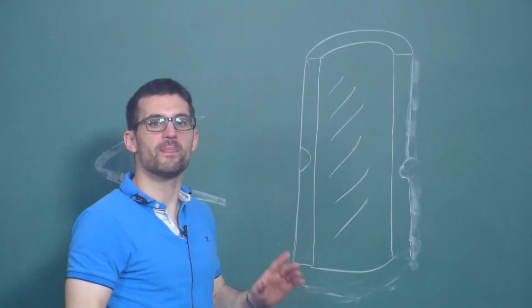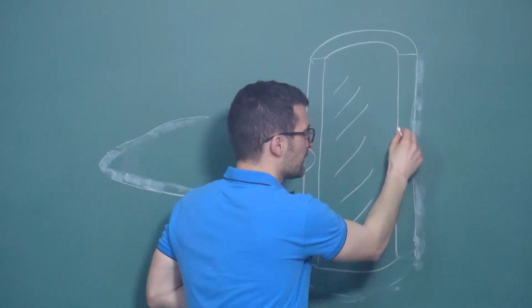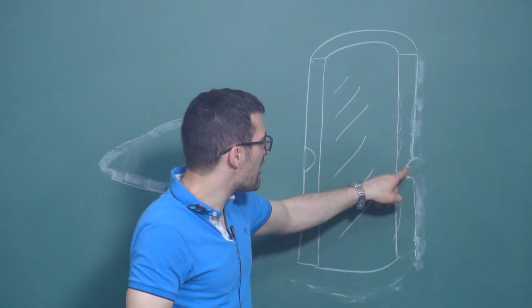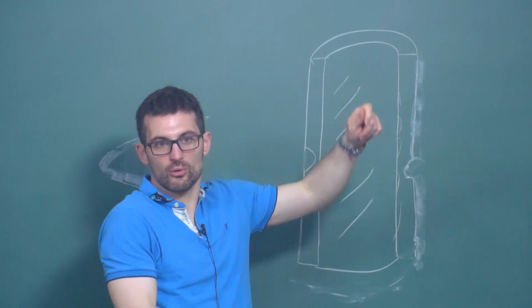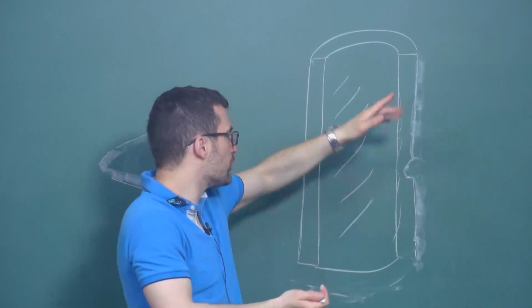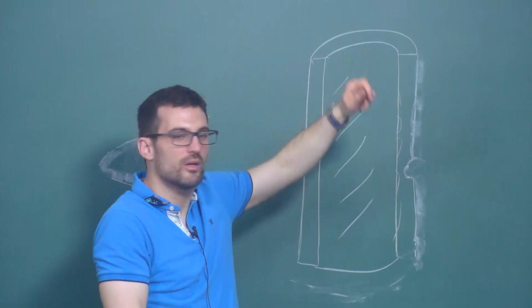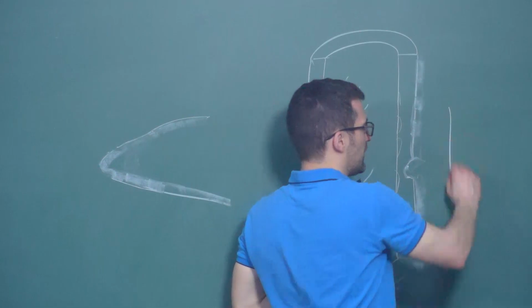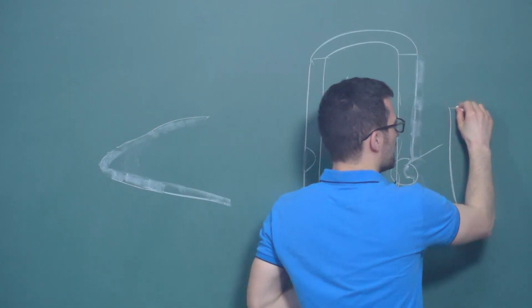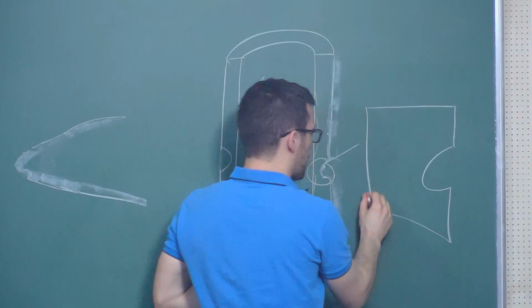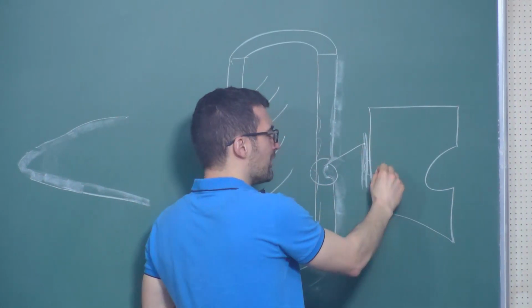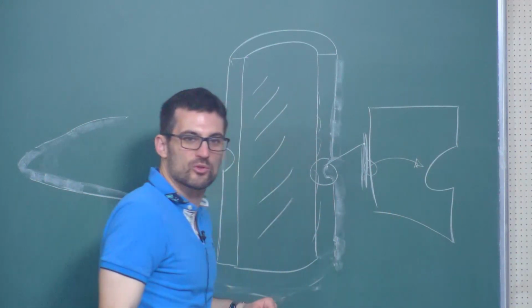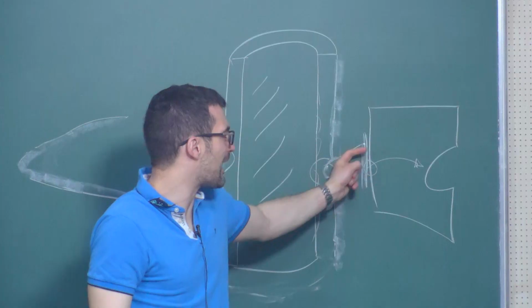So then he said, if failure happens here, in the inside, this means that it's anodic dissolution that is driving the process. But if failure happens near the notch, before, he also did some tests in air. In air, you'll get failure in the notch, but you'll get it at a very high load. If failure happens near the notch, that will mean that it's hydrogen driven. Because remember, if I zoom in here, you'll have some corrosive reactions happening here. That will generate hydrogen atoms. And remember, those hydrogen atoms like to go to areas of high hydrostatic stress. So if my cracks are here, this means that my hydrogen actually travels there.